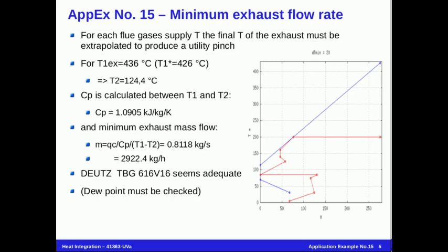And now the calculation for the flue gases. As we have 2 points, we can extrapolate the final temperature, the outlet or stack temperature of these flue gases. This is 144.4 Celsius, not displaced, the real one. The displaced temperature is smaller than that. For this final temperature, you must check that the dew point is not reached, in order not to have an acid stack, a condensation of the flue gases. Well, the water content in these flue gases.